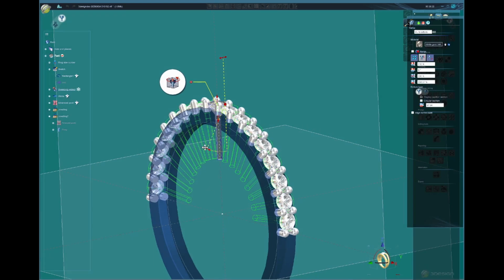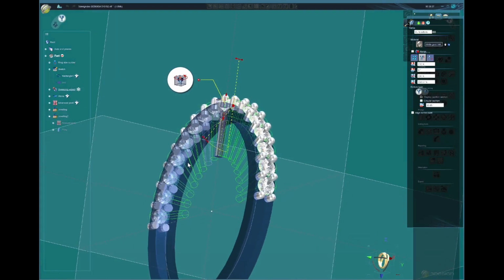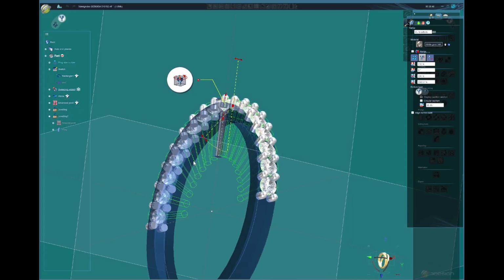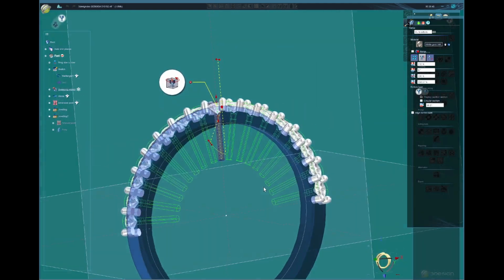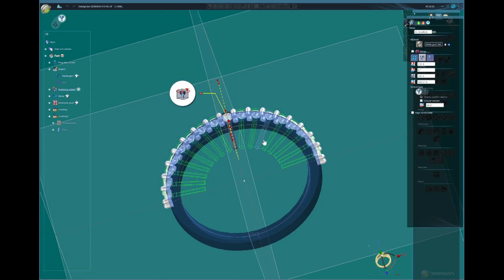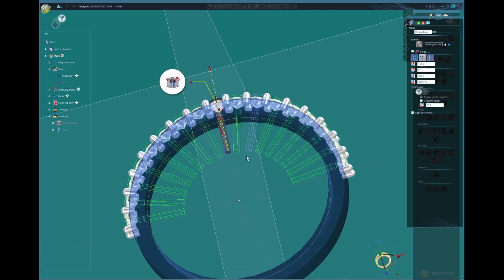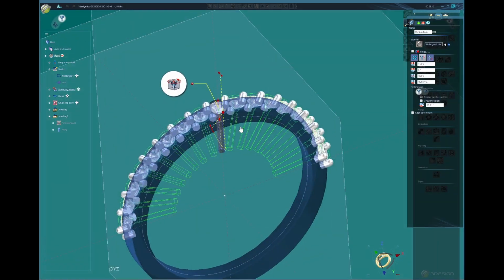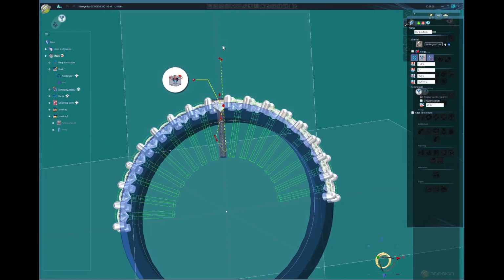See, when I move here, you see that my degrees here on the cutters change. Of course, you're not going to make a hole that big unless you want to. This is all your design style. So I usually do this. I think it's enough, even a little less. I don't recommend going too small on the hole because if you have a very small hole here, when your piece goes to casting, the holes are going to trap investment and that's going to mess up the whole casting. So don't make those holes too small and not too big either. Just nice enough to be pleasant to the eyes.